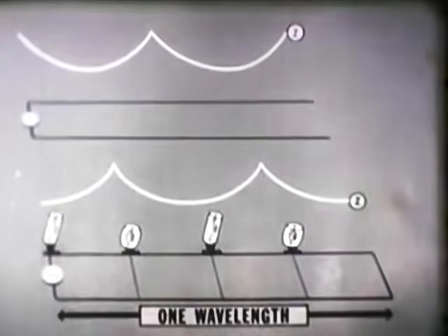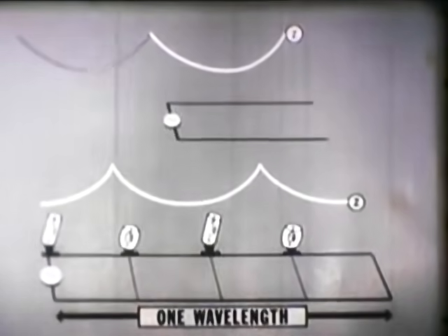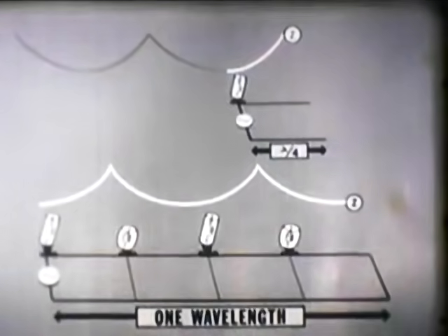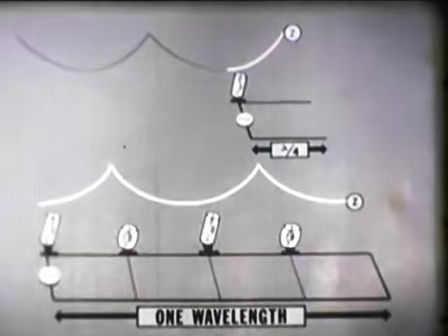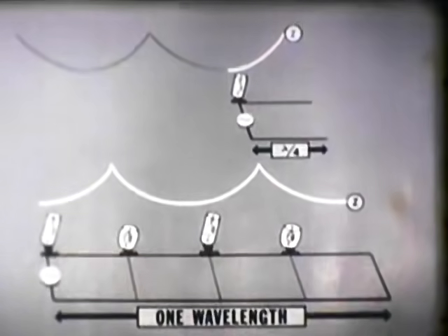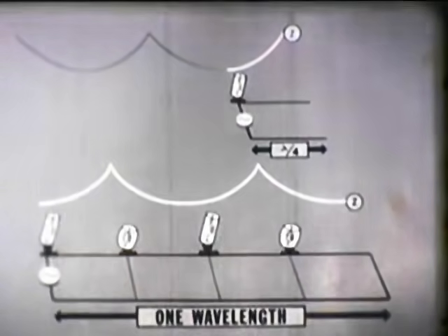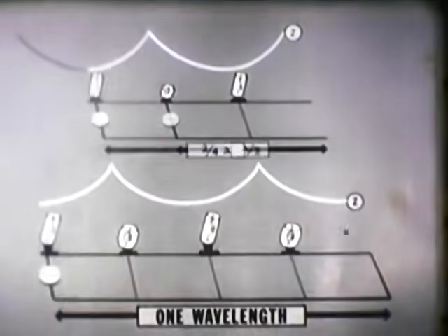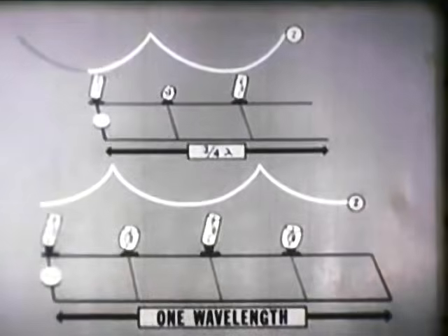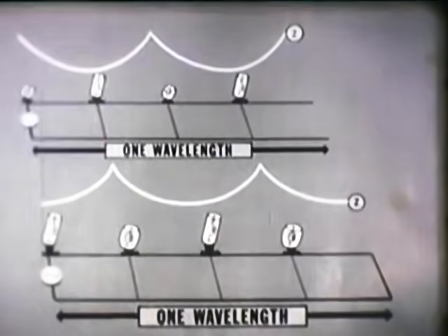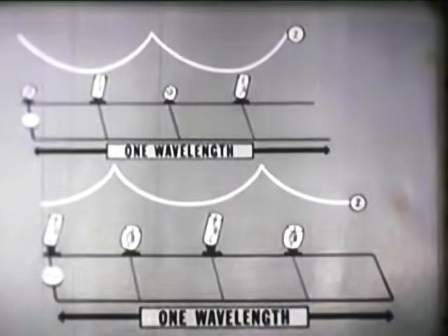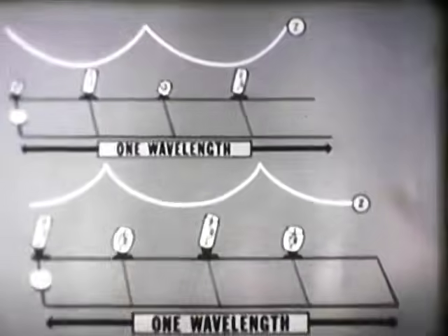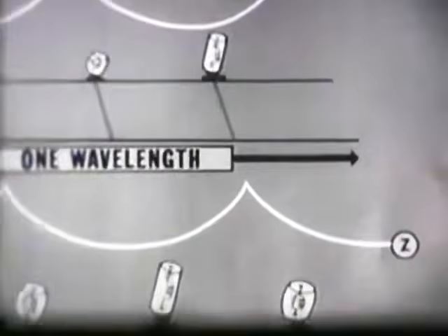The behavior of our open line can be investigated in the same manner. At the quarter wavelength point, the generator sees a condition of minimum impedance. This circuit can then be considered a series resonant circuit. Each time a quarter wavelength is added to the circuit, the condition changes. Thus, open and closed-end lines can be used as parallel or series resonant circuits, according to the length of line used. Because of this facility, they are known as resonant lines or tuned lines.